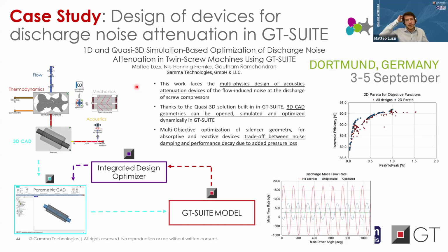What you see right now on screen was the absorptive silencer, which is using a very thick wool-like material to damp pressure oscillations coming from the machine. But of course, more basic formulations, like having a number of tuned chambers and baffles with perforated tubes and channels to create resonating chambers, like Helmholtz resonators, to dampen the pressure pulsations in the same measure but without the need of such material, can be analyzed as well. Both kinds of geometries are fully handled in GEM-3D as of today.